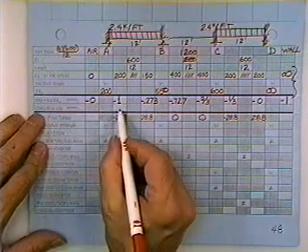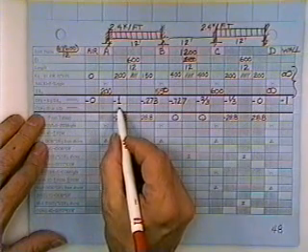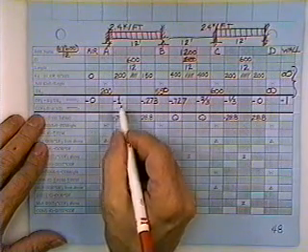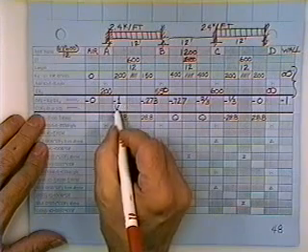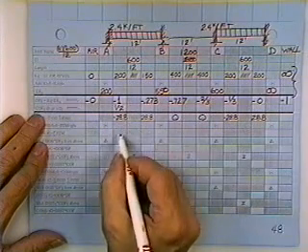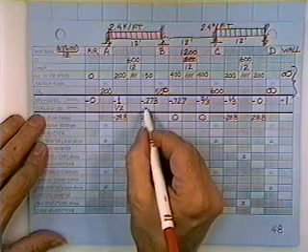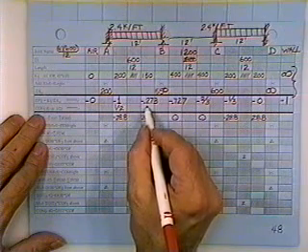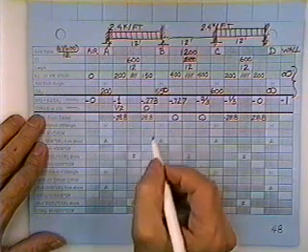So, I stand at joint A and look towards B, and since I see somebody down there on past B, the carryover factor is 1/2. When I stand at B and look at A, all I see is a pin and it quits. The carryover factor is 0.